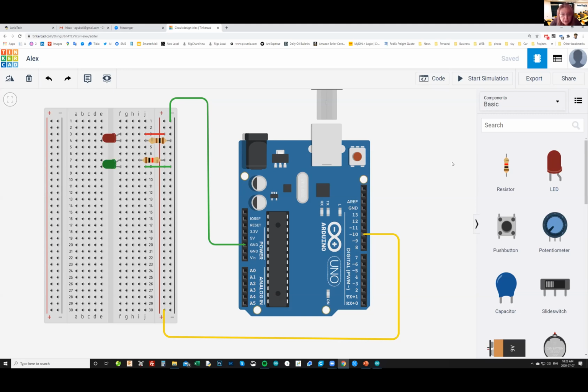And some of them, Alex, can you explain? Some of them have interesting signs in front of them. Like 10, for example, has a wiggly thing in front of it, right? So does that matter or not? Well, we shouldn't be concerned with that for now. We will cover hardware interrupts and things like that later. For now, all we need to pay attention to is the pins on the left with the letter A and the pins on the right that are digital. Since we will be introducing sensors today, and we will be working with analog sensors, we will be connecting them to this part in here.